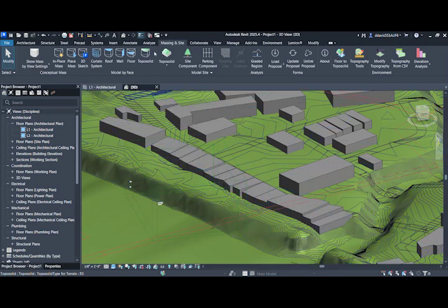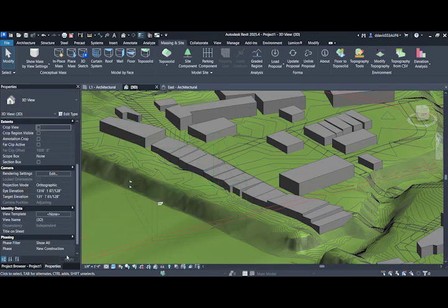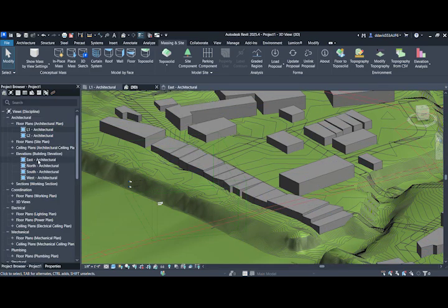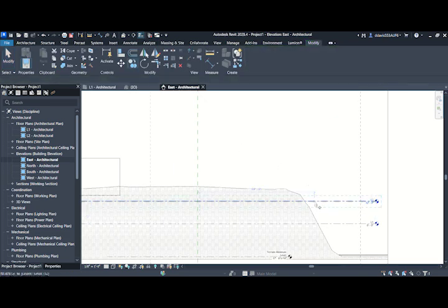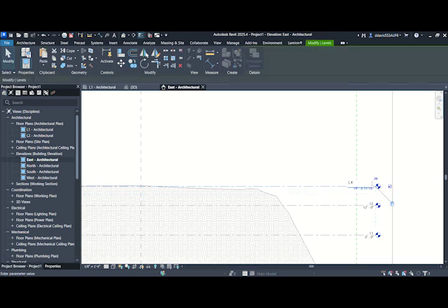This means that a tree in a BIM landscape can have all information required to install that tree, such as root size, condition, install height, water and sun requirements, and mature growth dimensions. The main benefit workflow-wise is that all information for documentation comes from the model itself.